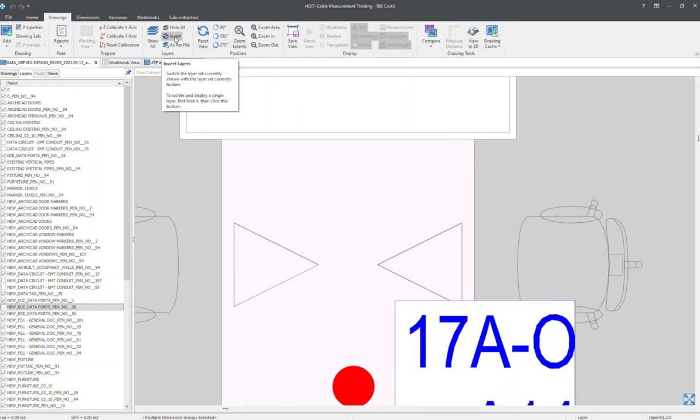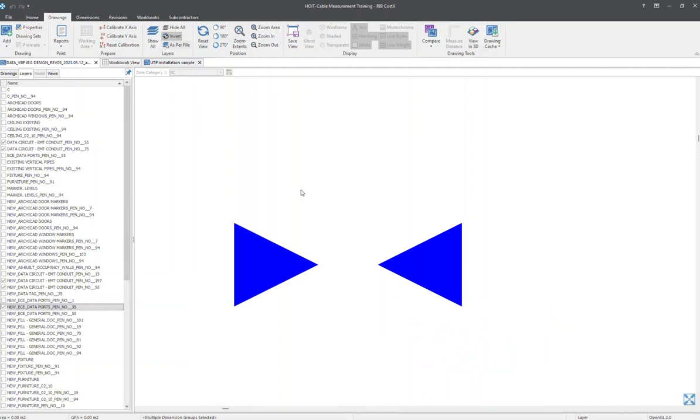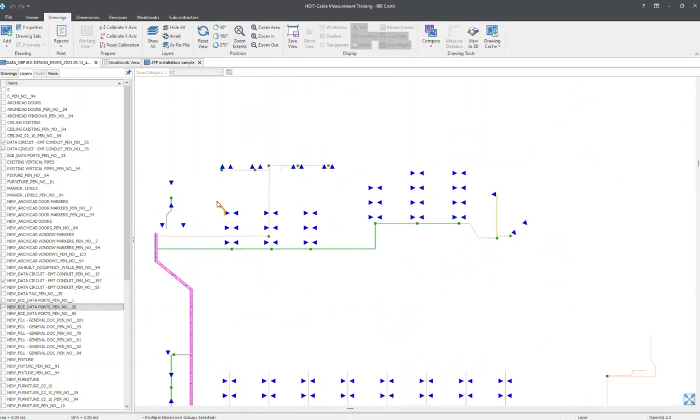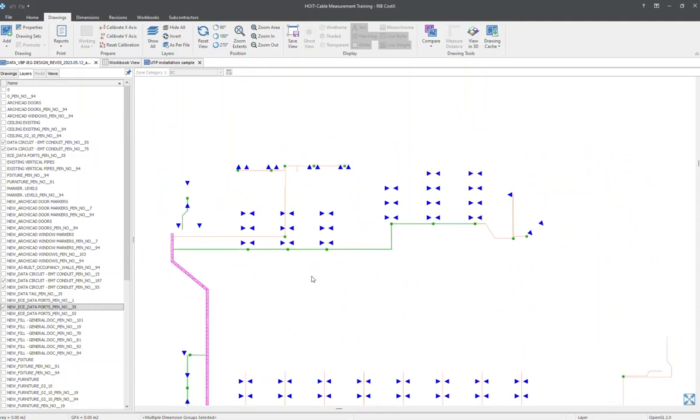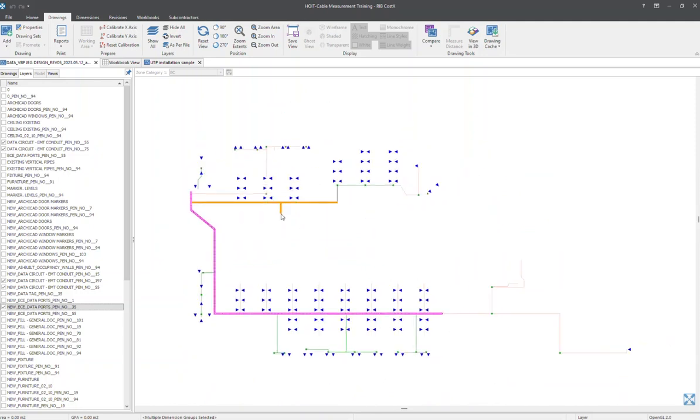invert. Basically the invert button is going to flip everything. It's going to flip everything that we untick now is already become tick. So when I click invert, then only the things that I untick just now become hidden. That is another trick or another tip that we can make the process of filtering layers much quicker and much easier.